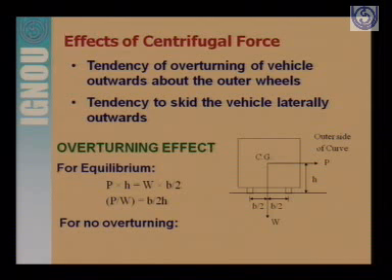This force P creates a moment P into H, which is trying to overturn the vehicle towards the outer side of the curve, about the outer wheel of the vehicle.